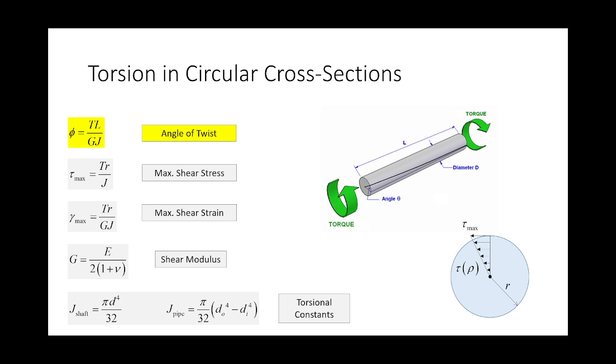So that's why if we didn't have warping effects in I-beams, we wouldn't be able to use I-beams for design at all. Like, they wouldn't work, okay? But circular cross-sections do not warp. They simply rotate, okay? So whenever you're on the FE exam, your torsion problems will be circular in nature. And if you get a question why, circular cross-sections don't warp, okay?